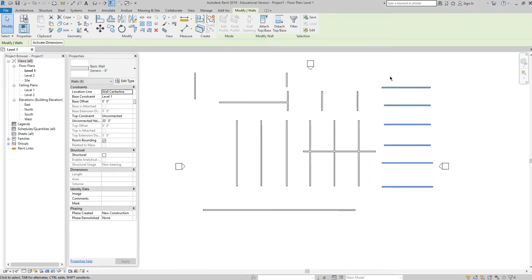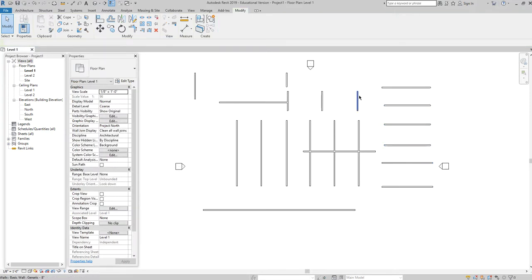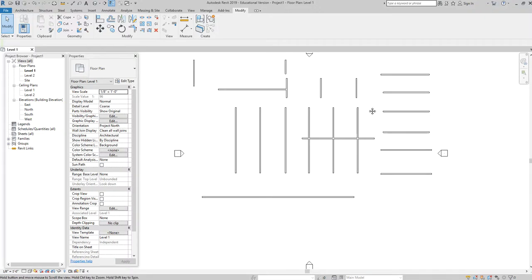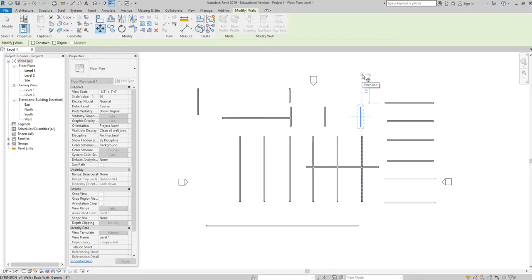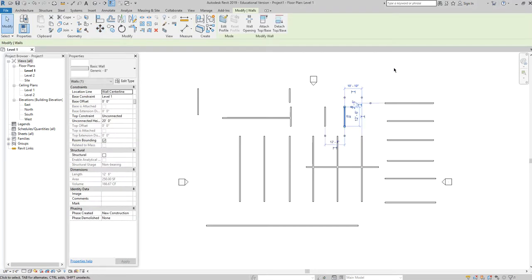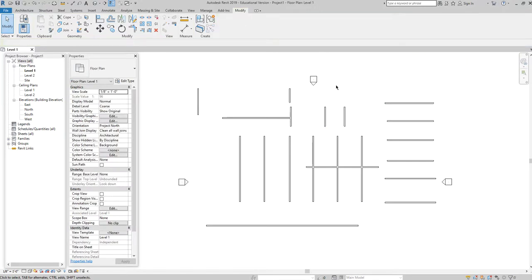Funny enough, though, unless I'm maybe moving an entire group of things, I don't find myself using move a whole lot, which in AutoCAD I use it all the time. I find myself using align instead of move because it's maybe more accurate in that it will align things to each other, right? So I find myself using probably align a little bit more than I do move. But that is what the move command does, right? So select MV on the keyboard. Click, move in the direction I want to go, 10, enter. All right. Now, that's our formal move command.